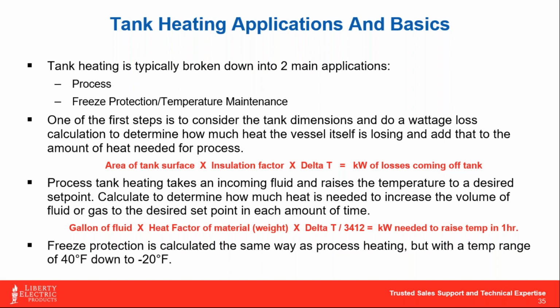I'm saying this because if you want to change that time, everything's based on a 1 hour heat up time in our world here with electric. So if you need it in 15 minutes, I have to actually not only double but quadruple the size of that kW output to get it down to 15 minutes.